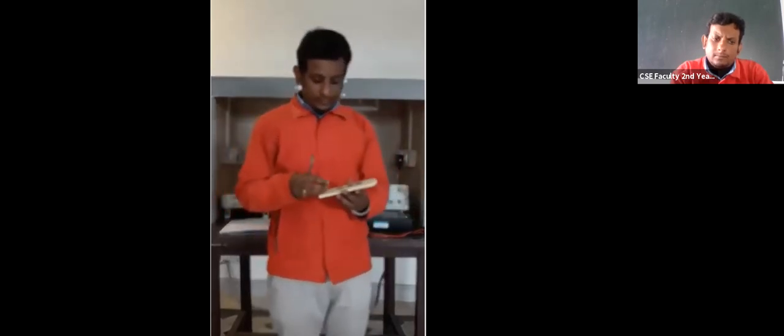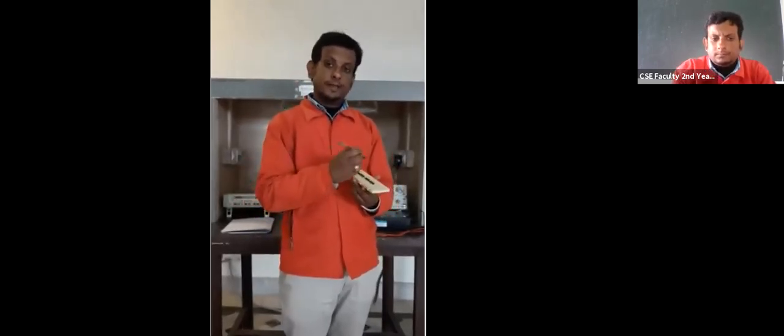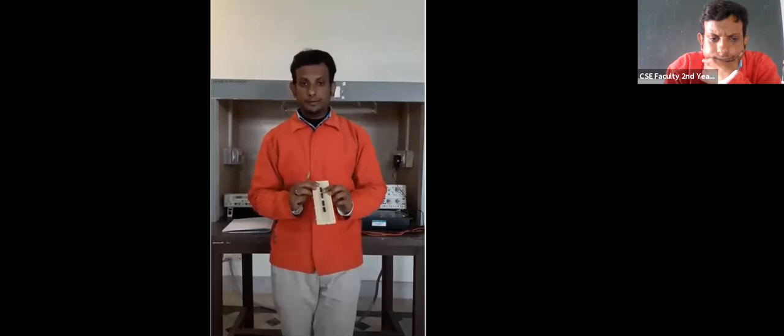Please keep in mind, this is the breadboard and this is the IC, and with the help of the breadboard, the IC and connecting wires, we can build the circuit and easily perform the laboratories. But when we want to perform the laboratories using a breadboard, we need a power supply so that we can give VCC and ground to the IC. VCC is the power supply for that IC, and a ground terminal is also there.